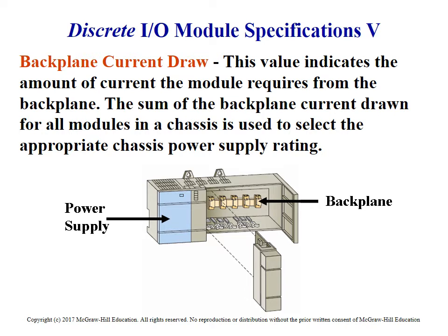This is a configuration thing, something that I don't see you guys getting involved in right away. But if you do get into PLC design, layout, that kind of thing, the PLC power supply is kind of critical when you're designing a racked or a modular system. You need to know how many cards are going to go in your rack, and how much power each one requires, to size the power supply properly.